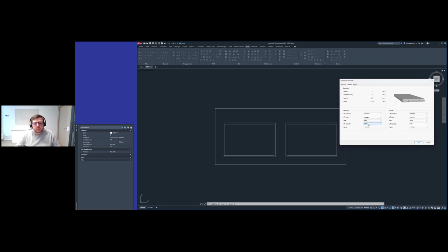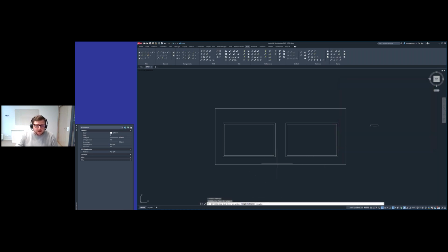So I will use my definition, and in the backside, as I have here, I want the lifters to have the capacity of lifting 100% of the elements, because these ones I will use when I demold it, when I transport, when I handle it on the storage yard. And then in the front side, I will only use them for when placing the actual balcony on the building. So then I have the possibility to say that, okay, here I just need ones that can handle 50%. So we draw it, and we draw a single one.